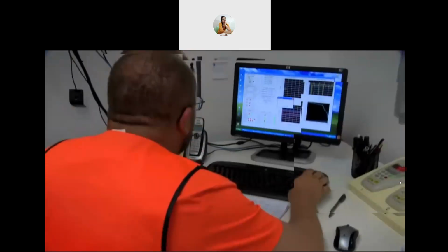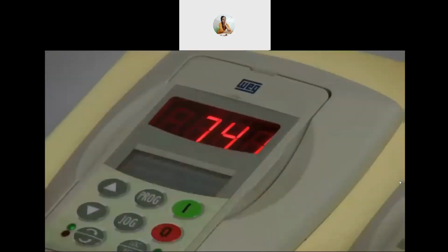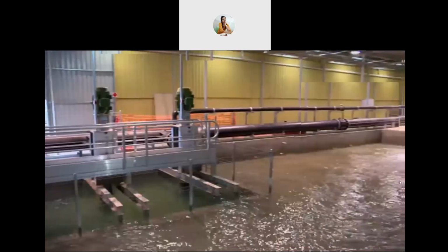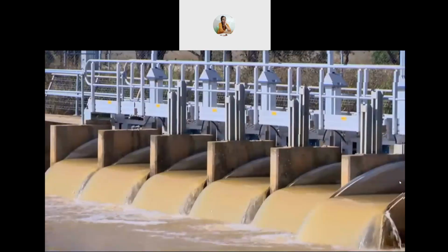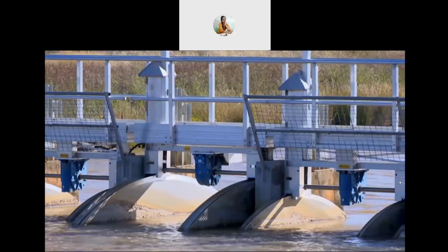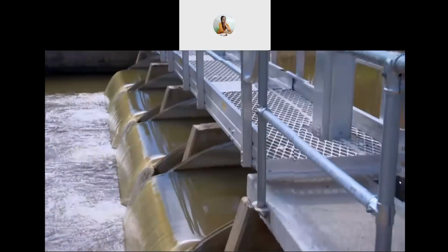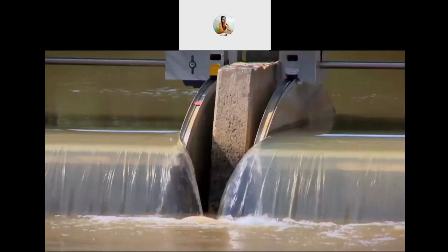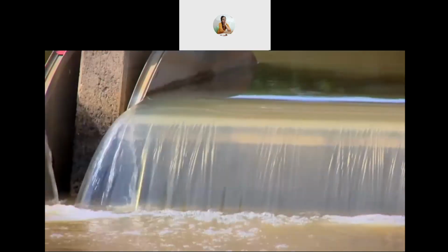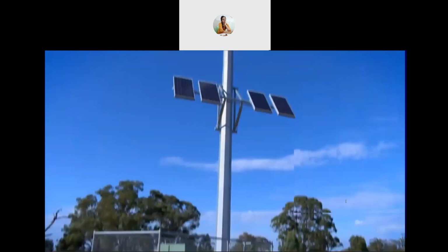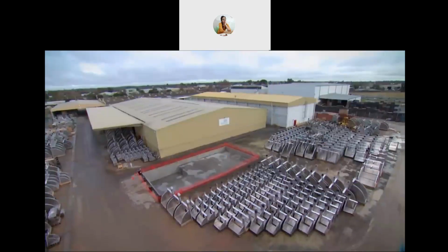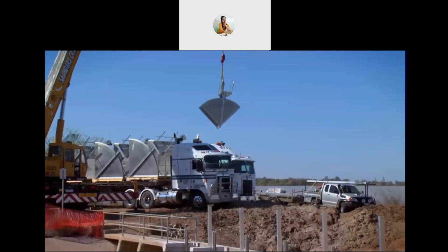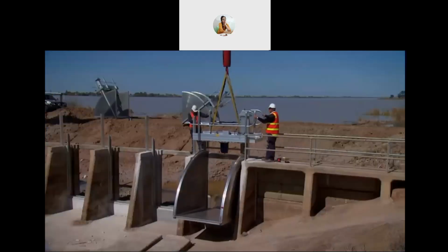The project's technology is the result of many years of research and development undertaken in conjunction with the University of Melbourne. Called Total Channel Control, it is the world's first fully automated end-to-end canal automation system, enabling efficient operation that is on par with pipe networks, but without the associated costs. It achieves these outstanding results using a combination of precision water control gates, known as flume gates, accurate system-wide flow measurement, wireless radio networks, automated meter outlets, and sophisticated software. The project is transforming the district on a large scale, with some 10,000 flume gates being installed across thousands of kilometres of canals.